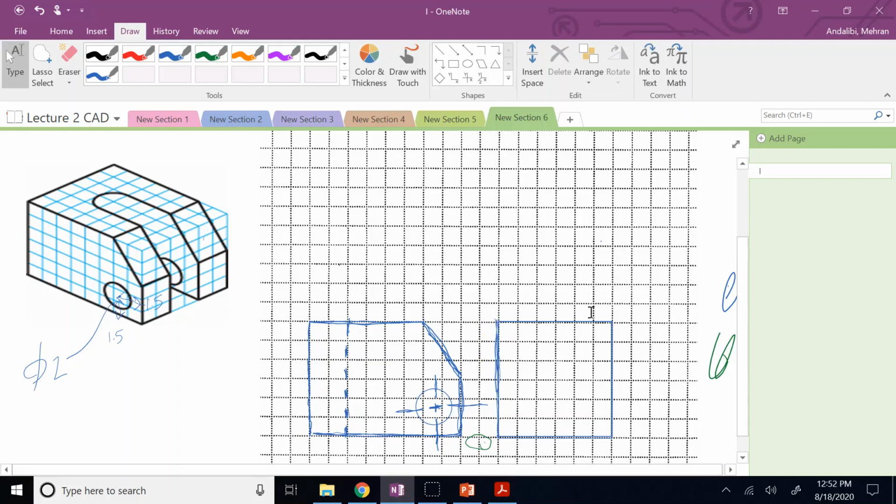And then these two guys are both 3 by 2, so they go like this. And when projected onto the right plane, they would also be 3 by 2. So they would appear like that. The top portion is the inclined one, the bottom portion is the flat one, and similarly on the right side. Now, this curved surface would appear as the rectangle.